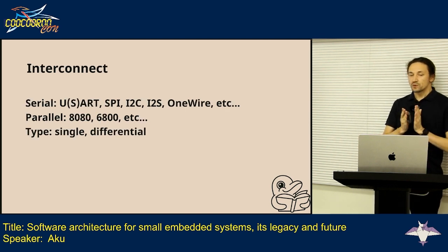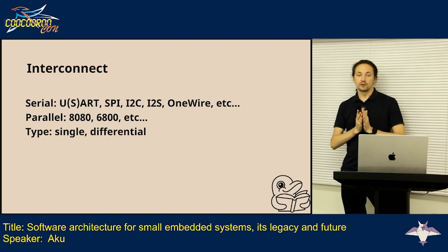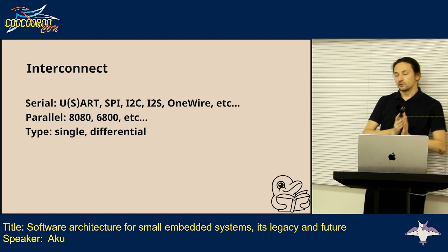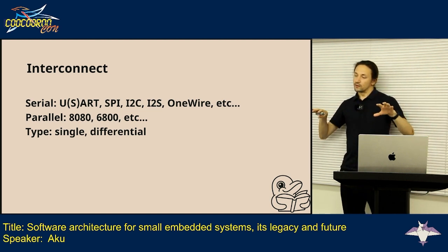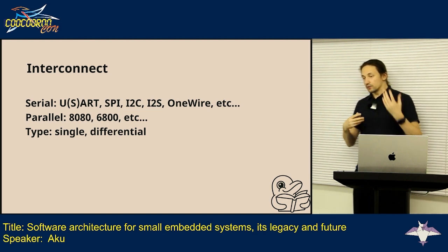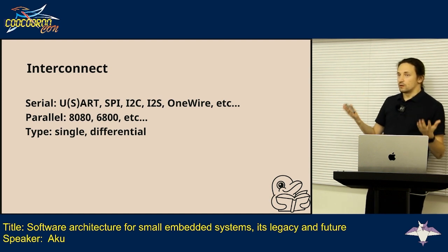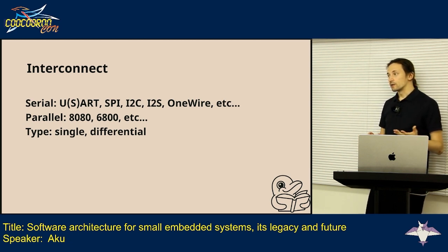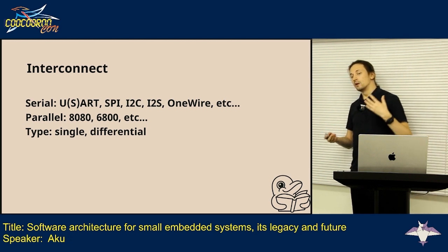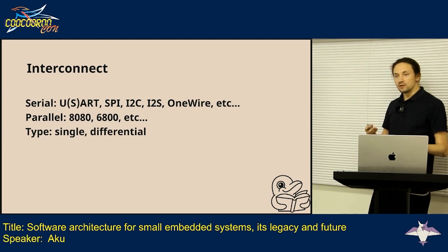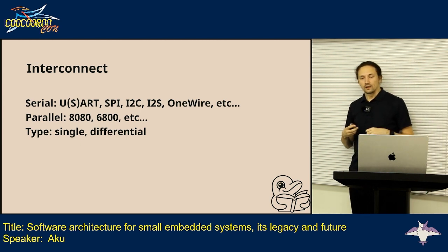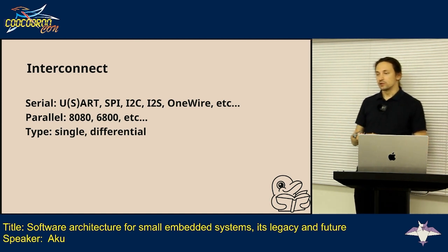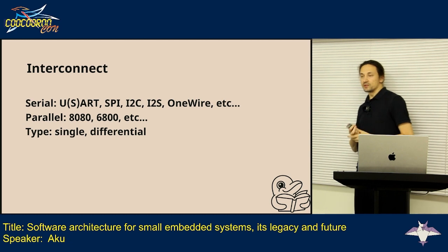So if we're talking about MCUs and CPUs used in embedded, you usually have a bunch of different buses to connect all those different parts of your system together. If we're talking about, let's say, cars, the most popular one will be CAN bus, and usually your car has at least a couple of different CAN buses with different speed and different levels of redundancy. Let's say we have the engine, then brakes. This probably will be the most important.